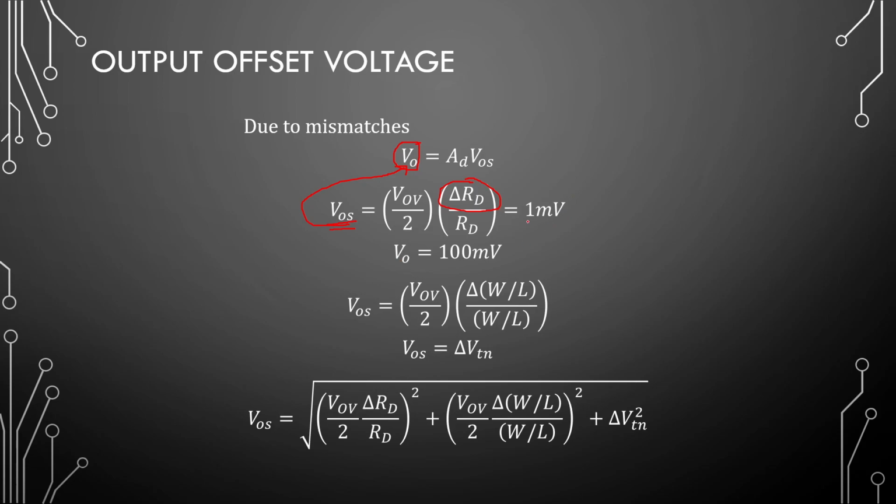Right, so this one is easy to simulate. With our gain of 100 that we calculated earlier, this will be 100 millivolts of offset. And this is only for differential mode. For single-ended, your output offset will be the drain voltage plus whatever this small amount of voltage is. So typically for the single-ended conversion, you need to take the output through a capacitor, which removes these offset voltages in any case, unless you're using that voltage to bias a next amplification stage.